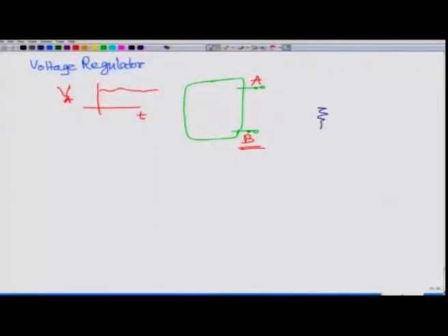and this needs a constant voltage. What I will do is connect it here, and then I put a resistance here known as the shunt resistance, R_S, and then I put this Zener diode in reverse bias condition, and say this whole thing is my supply now.